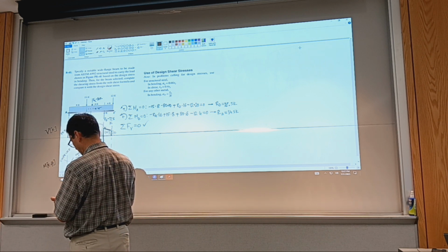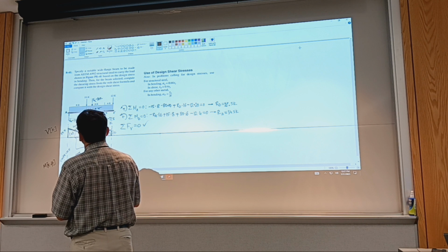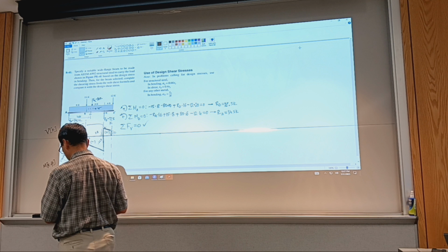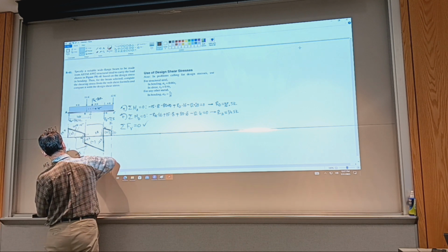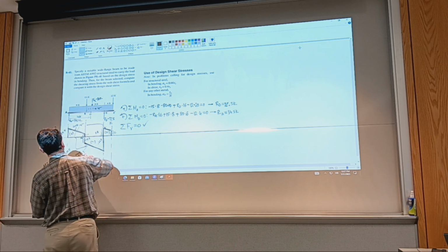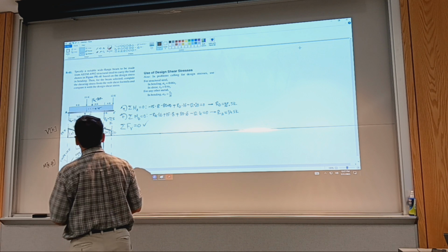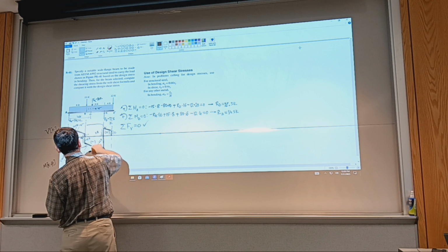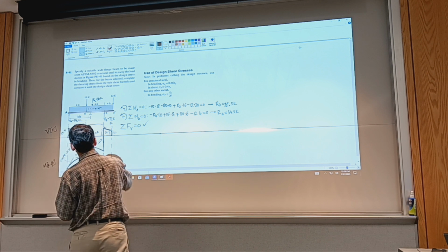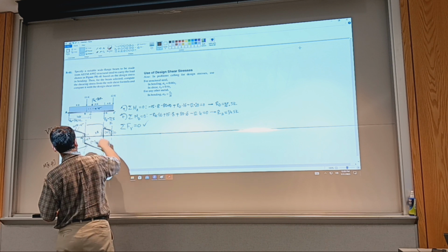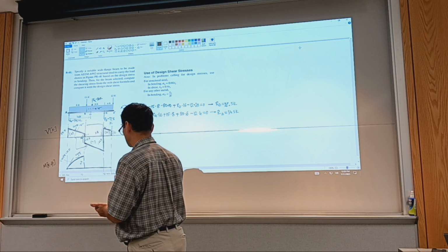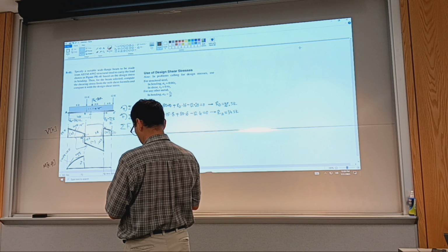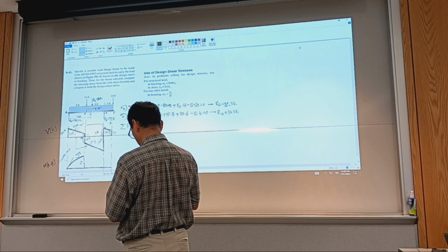34.5 plus 2.5 times 8 over 2. Okay, so it's 148. 148 is the moment at B. To get the moment at D, I need to add the negative area of the second trapezoid to this positive value. There are 3 trapezoids. So I said negative, let me put this in the memory and start fresh.